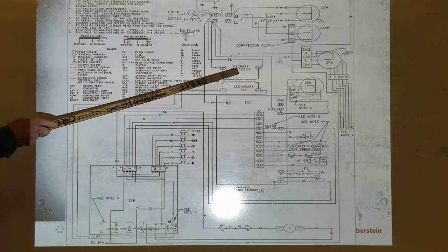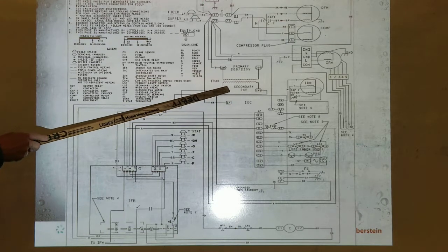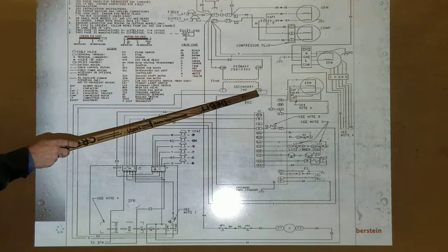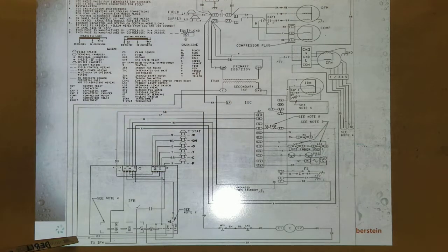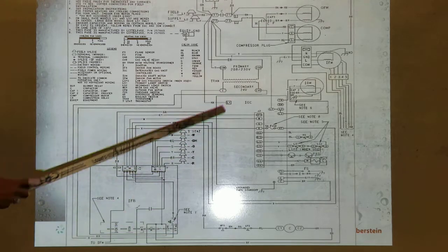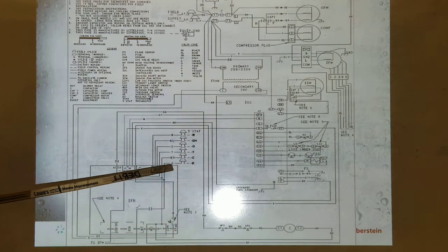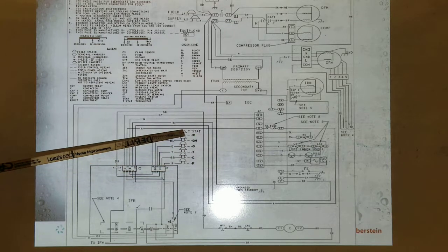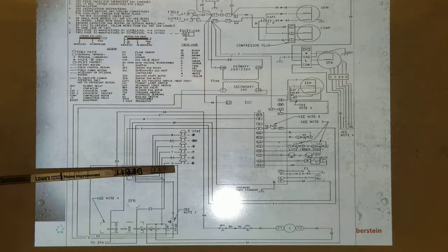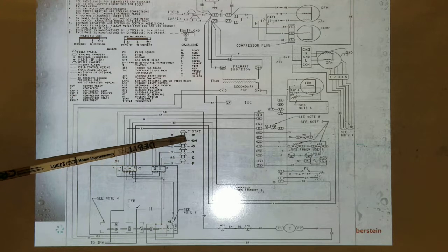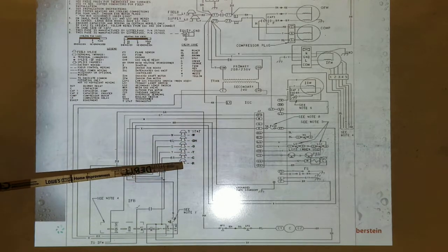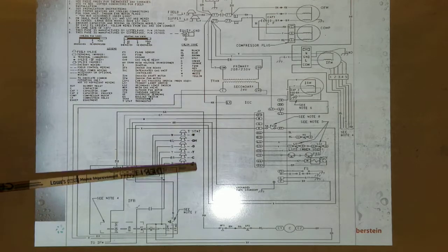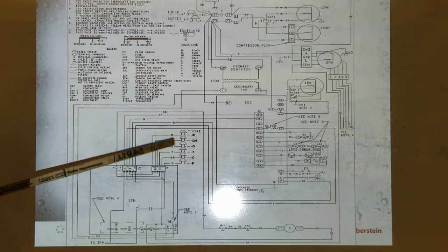It says primary and secondary, right? So here's your common wire and here's your 24-volt hot. So this is the red wire. It's coming down here, and you know that it's gonna end up at this red terminal, because all these little things right here are wire nuts. That's saying that this is going to the thermostat. That's field wiring. So here's all your colors on your thermostat. You know that's all on the low voltage side.